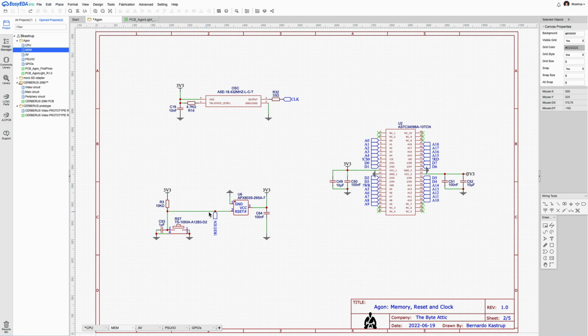In the beginning, because the capacitor is discharged, this point will be low at ground level. And therefore, the reset will be active, because reset is active low. So when you turn the computer on, this line will be low or active. The computer will be in a reset state. But with this trickle of current slowly charging the capacitor, after a few fractions of a second, this will be high, and the reset signal will go high and therefore inactive. And then the computer can go into normal operation.